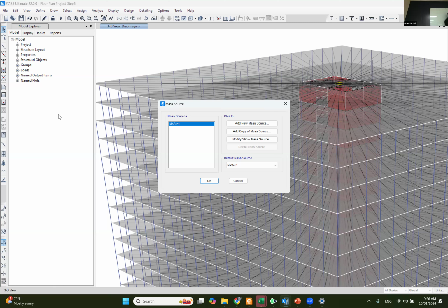So we are going to assume it's dead load plus a factor, let's say Xc, multiplied by the live load. This one, sometimes it's 0.25, sometimes it's 0.5, sometimes it's 1, all right? So what ETABS is going to do for us is solve this dynamic equation. If you guys remember, this is a second-order differential equation. The software that we're going to use is going to tell you, once it's solved, what u as a function of t looks like.